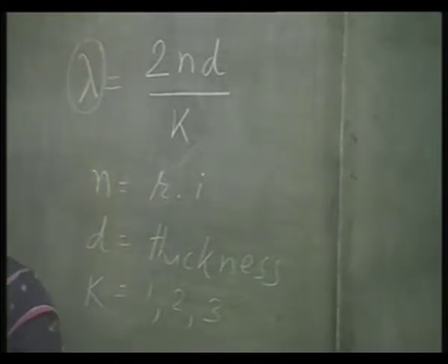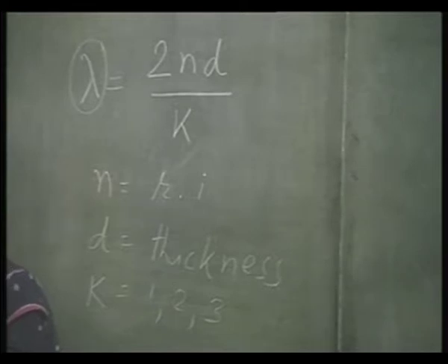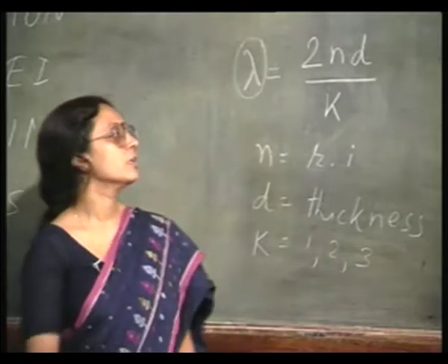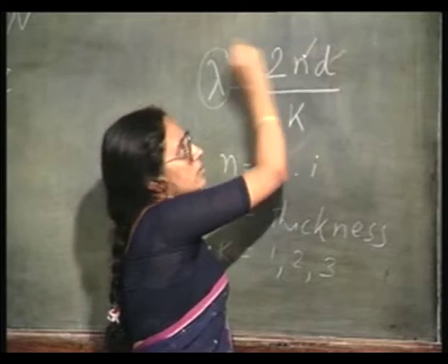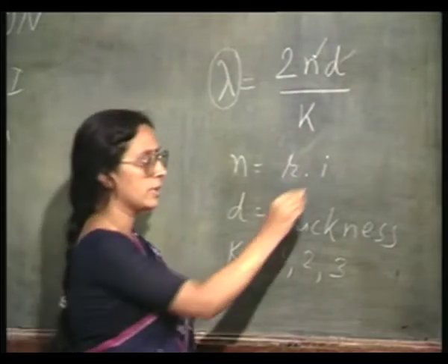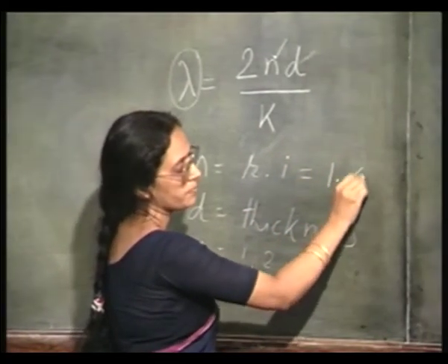That is why when there is oxide on silicon film, depending on its thickness, it appears differently colored, blue or pink, something. Now, the refractive index of silicon dioxide is known, and that is 1.46.